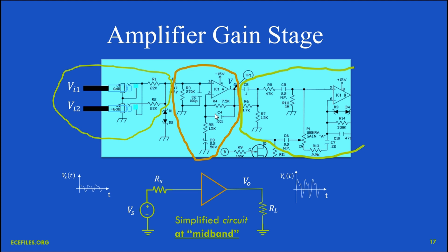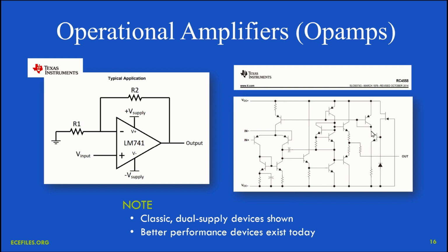And likewise for C4 and for C3, it acts like a direct connection to ground because it's very big. It's 2.2 microfarads. So we just have this resistor R4, this resistor R5, and R3 over here at the input, in addition to everything that's inside this amp. Oh, wait, we can simplify that. That's what we're trying to do here.